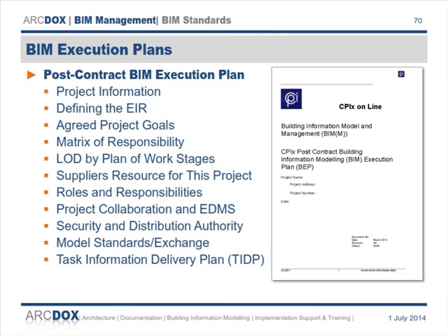And this is the document that really says how you're going to deliver this project. Okay? The pre-contract BIM execution says how you intend to deliver it. This says this is actually how we're really going to do it. And we now have all these things in place. We have the matrix of responsibility. We have the levels of model detail. We have all the roles and responsibilities defined. We have all the collaboration processes in place. All the security set up, done, all in place.